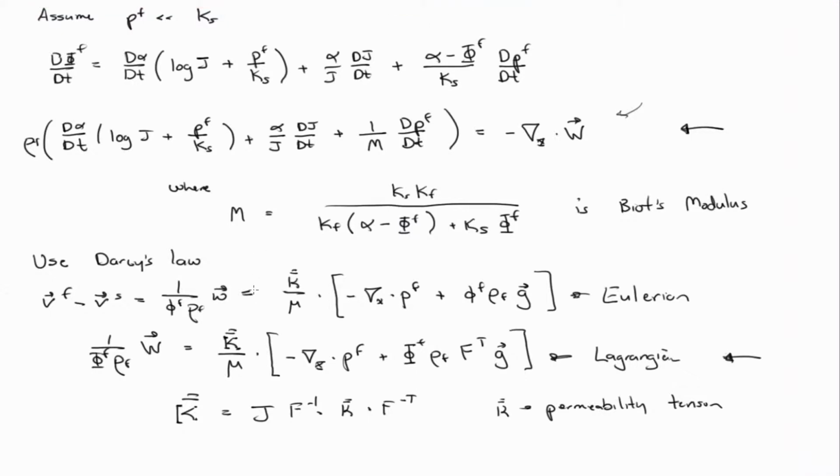Okay, so just one little mistake in the notes last time. When we defined this Darcy flux, I accidentally put the volume fractions in there. They shouldn't be there because by definition, this is the velocity of the fluid with respect to the solid, right? So it's not some partial velocity, it's not the total velocity where we're taking the partial volume to get the partial velocity. It is the velocity of the fluid with respect to the solid by definition, okay?